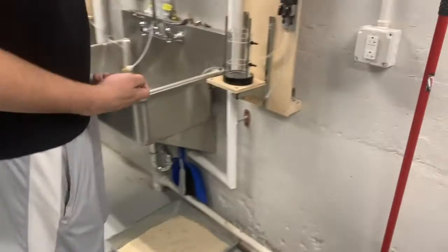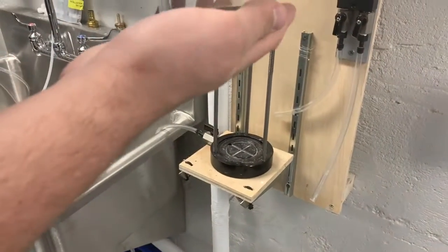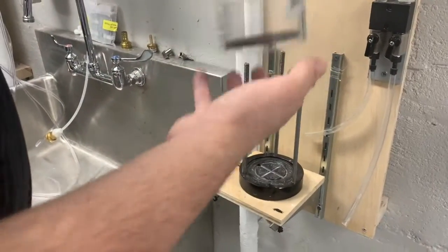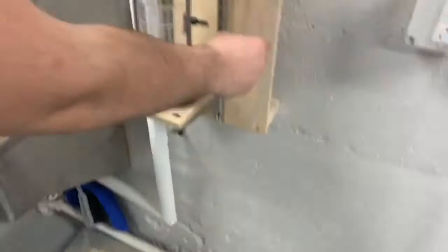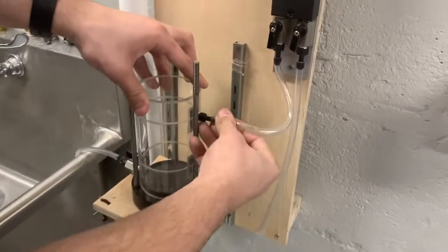Find the porous stones labeled with a B. This will be placed in the bottom of the test apparatus. Place a cylindrical part in the base and ensure that the stone is flat on the bottom. Then you will attach the two tubes, the outlet to the manometer.